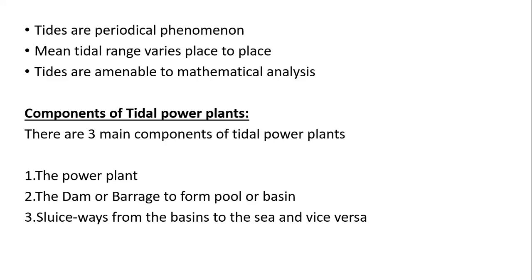If reversible pump turbines are provided, the pumping operation can be taken over at any time by the same machine. So if you incorporate reversible pump turbines, operation is possible for any direction of water flow. The modern turbines are very versatile, so that they can be used either as a turbine or as a pump in either direction of flow. In addition, tubular passages can also be used as sluiceways by locking the machine to standstill.